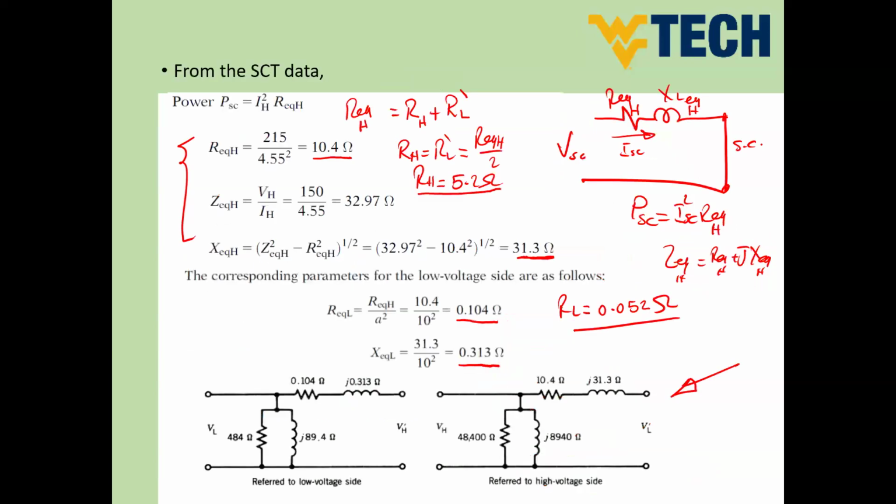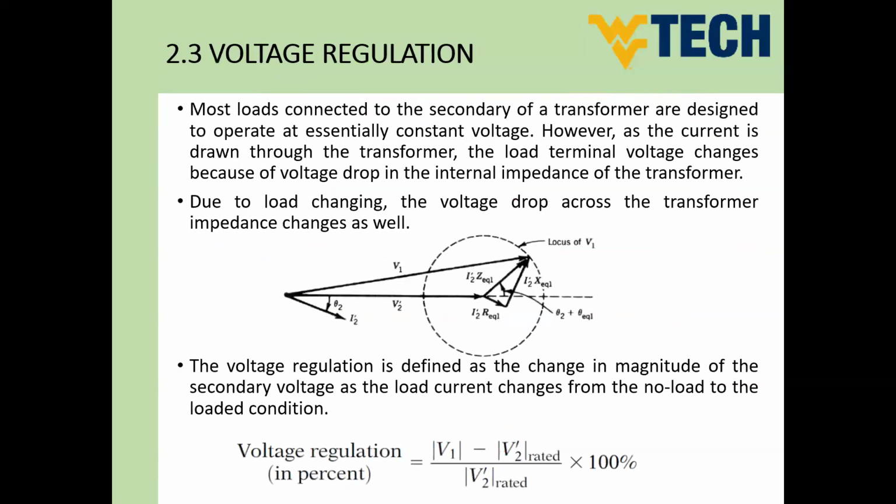Okay. And you would find that also in any other calculations in terms of is it V line or V phase. And all of the time, guys, for the parameters, we care about the phase value, because any parameter or any impedance by the end equals V phase divide I phase. Okay. So this is the only difference between parameters identification of three phase and single phase. We will care of getting the exact or the correct voltage and current representation in the calculation. Okay. And so we can now make any kind of parameters identification for open circuit, for single phase or for three phase transformer. Next class, guys, we will start from this point, which is the voltage regulation.